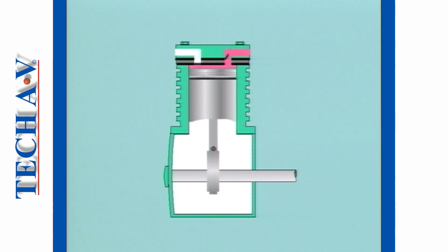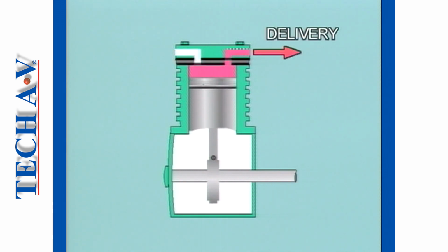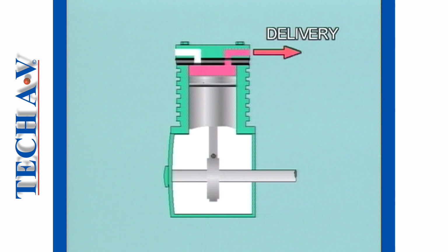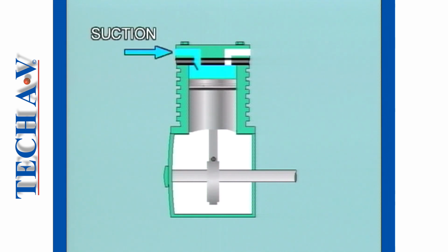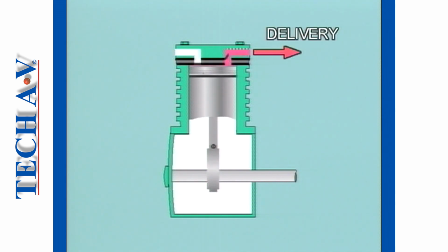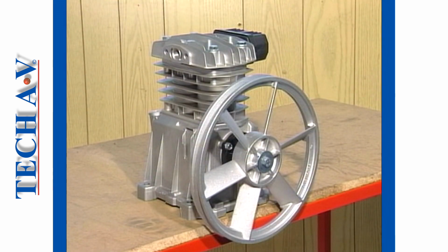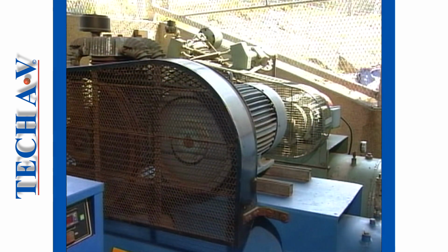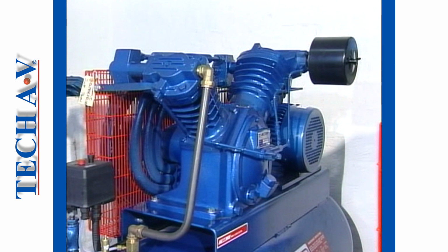Single-stage compressors discharge their compressed air directly into the system or into a receiver. In other words, full compression is achieved after one upward stroke of a piston. Single-stage compressors are usually quite small units, such as those used in small workshops or for home use. Where large air quantities are required or higher pressures need be generated, then a multi-stage compressor would be more practical.